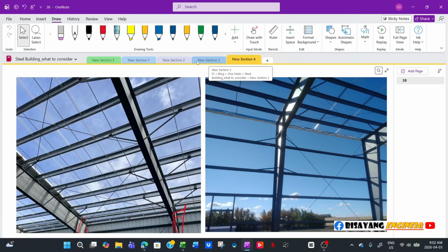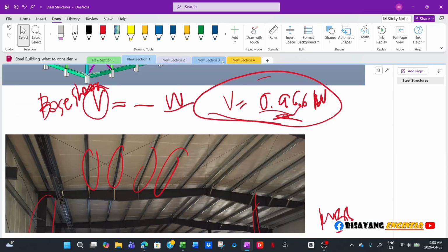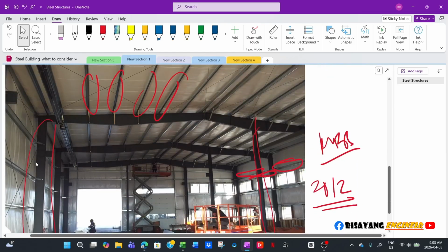And when I do my calculation, I use regular sections, and most of the time I will have W24, sometimes W27, W28, something like that. I think there was one where the span was 120 feet, and the section I got was W36 by 100-something.